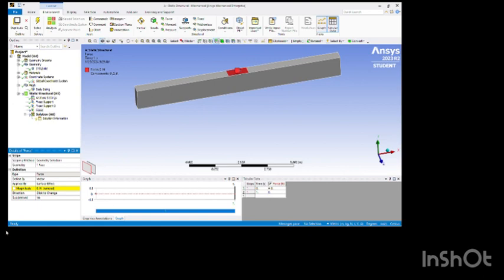So here we can divide it into components, because I want to apply the load downward only in y direction. So from here define by, then I will click components, and here I will keep all the other components like x component, z component as 0 Newton, while I will change only the y component.